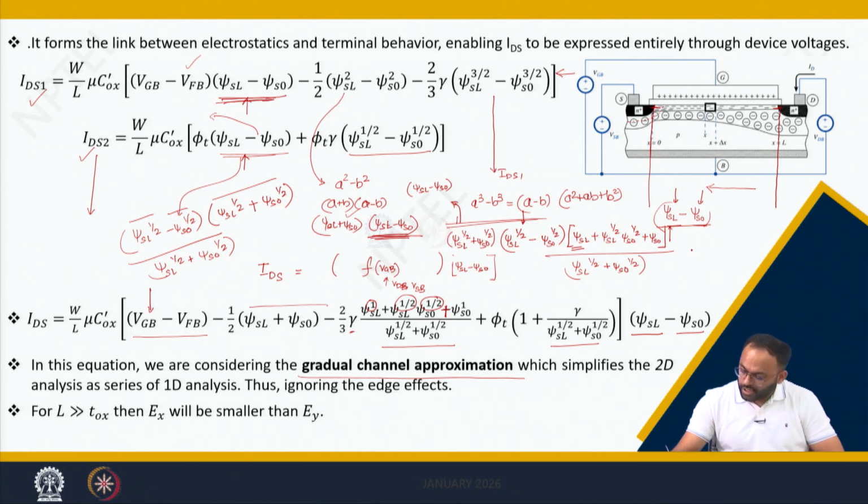You remember our analogy of fluid dynamics. We said that when we turn on the piston or when we open the piston, there will be a transfer of water from source to drain. So, the role of piston or the role of gate is to create inversion, and the role of VDS is to change the level of source and drain tank such that the carrier or water flows. That is what is causing a horizontal field.